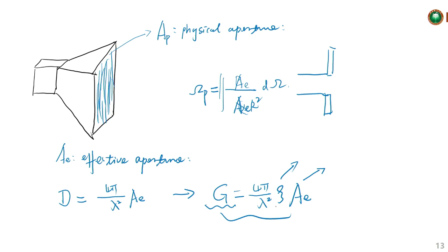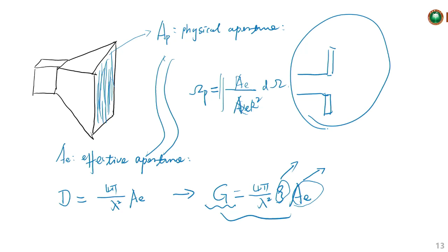But actually it does not always work, because we need to know the exact values of the antenna efficiency and its effective aperture. For horn antennas, the effective apertures and the physical apertures are roughly equal to each other, but for the dipole antennas, for example, it is difficult for us to extract the effective aperture here. So we need to find some method to characterize it.